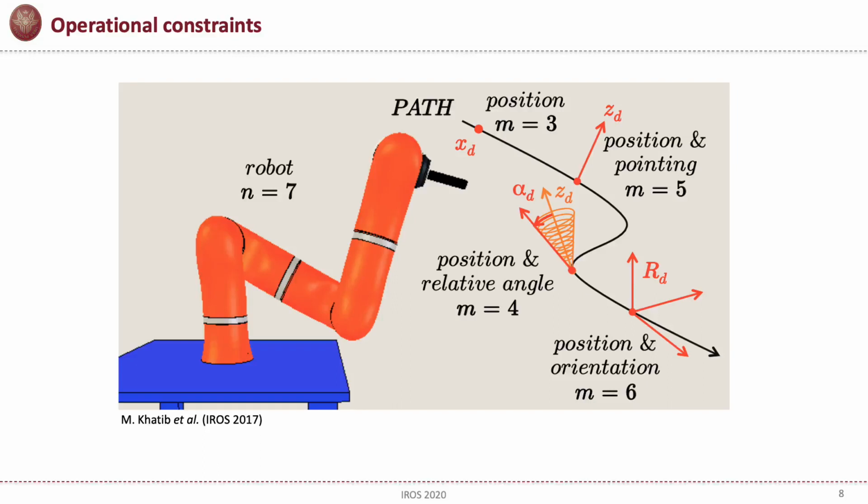Usually the Cartesian task for the robot end effector typically includes following a desired time-varying reference for position and orientation. In this case, the robot needs at least 6 degrees of freedom. The number of joints used to accomplish such a primary task reduces the capability of the robot to fulfill it while optimizing its motion with respect to other desirable criteria, for example, for avoiding robot body collision in the workspace. In this case, a possible reduction of the actual dimension of the primary task is preferred.